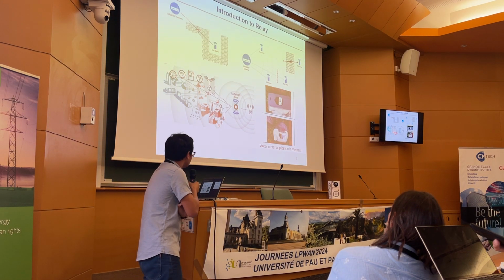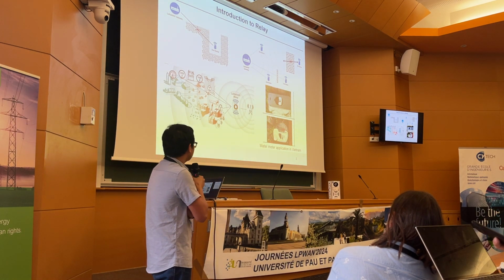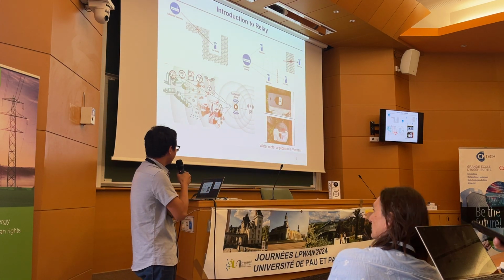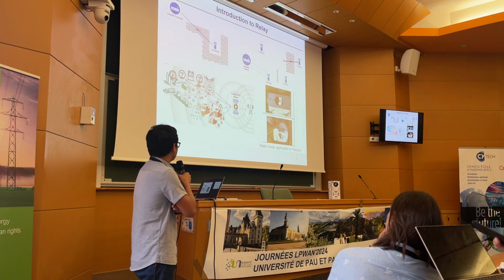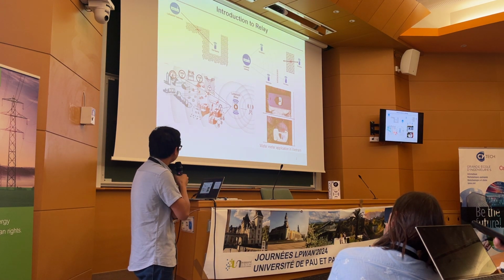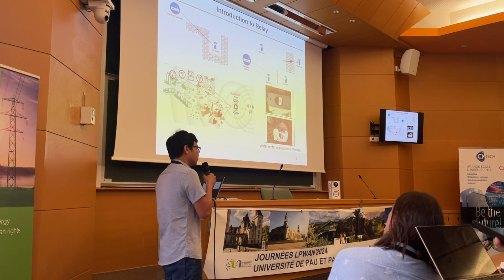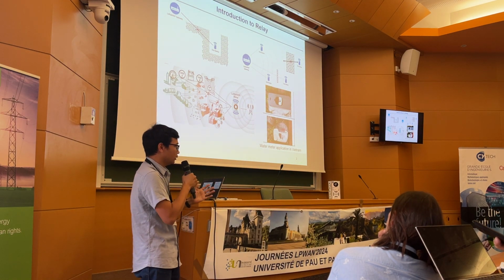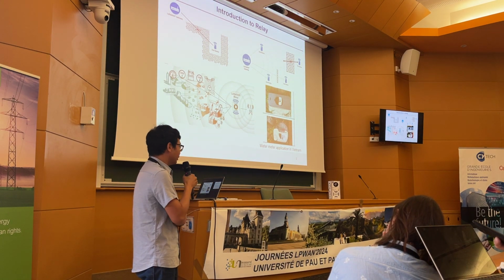I have some examples in Vietnam. They deployed several experiments with water measurement using LoRaWAN, but they also met problems with communication with the gateway, because most of the water meters were installed underground or inside a metal box, so it's very hard to communicate with the gateway.